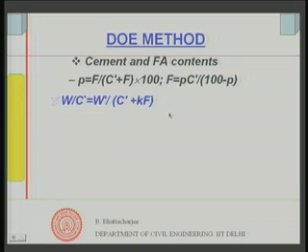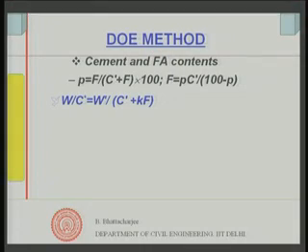Now I have water to cement star, which was there earlier. The equivalent thing when I am using fly ash is W dash divided by C dash plus Kf. You see, if I add F quantity of fly ash, all the fly ash does not contribute towards the equivalent water cement ratio. I can now define a term called equivalent water cement ratio. Equivalent water cement ratio is W dash, that is the water that you are adding, divided by C dash, that is the cement you have, plus F multiplied by K, Kf. So, this K is less than 1.